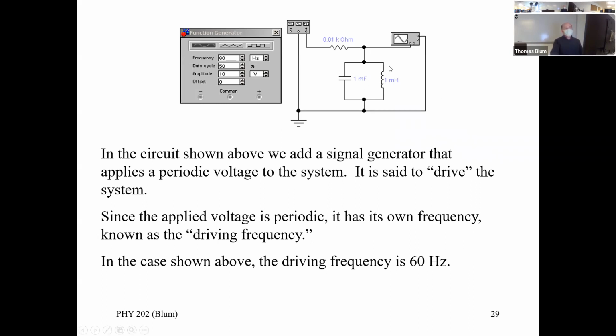So here's my inductor and my capacitor. That thing likes to oscillate. And now I've connected it to a signal generator, and that also oscillates. And so we have two oscillations. The driver frequency always wins.